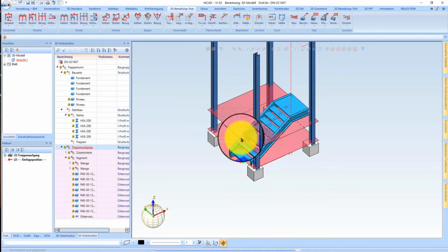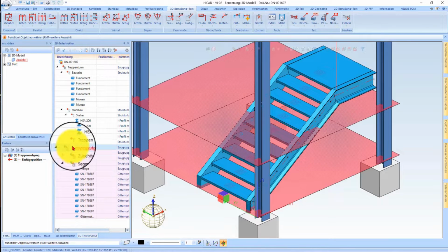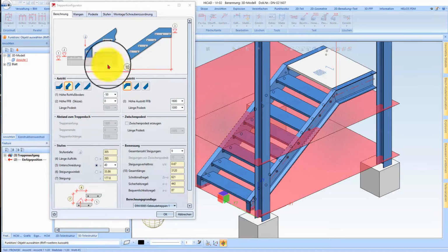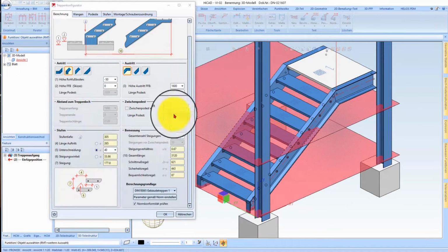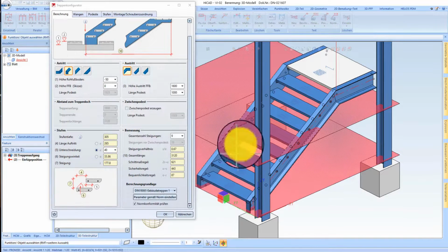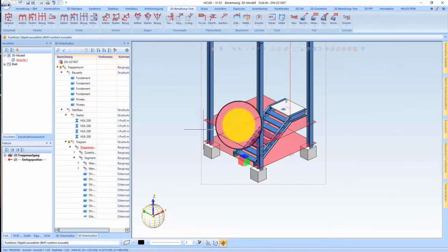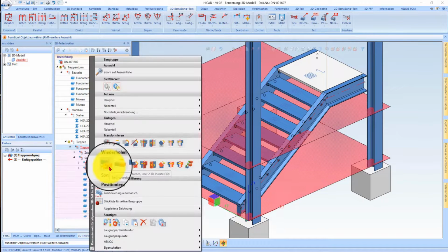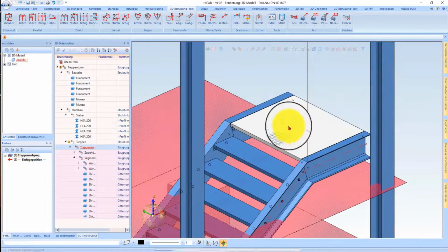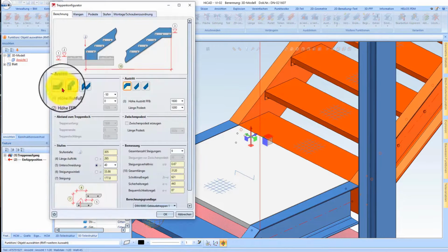So, of course, I will also save at some point. This means that, in principle, I can always go back into this staircase, which I just drag in here correctly, and I can also change the values, the difference, the tread of the intersection, values, heights, whatever, and I can change this at any time. It is important to note that it currently only applies to one run. This means that if, as in this case, the staircase continues, I essentially need to copy this staircase upwards. In other words, I simply copy it upwards, just like that. For example, go back into the configurator and simply change this one here.